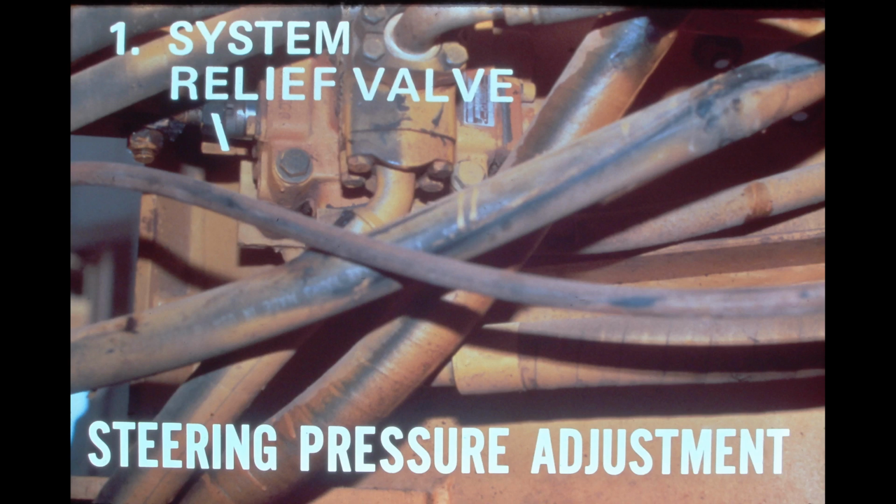If the pressure does not change, the problem may be in one of the other components mentioned. Remember that internal leakage will cause heat. Check the other components for excessive heat before replacing the system relief valve.